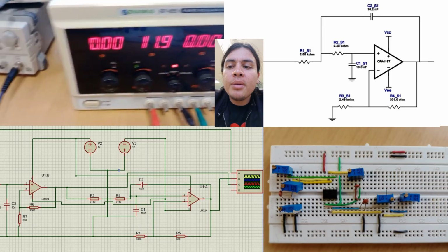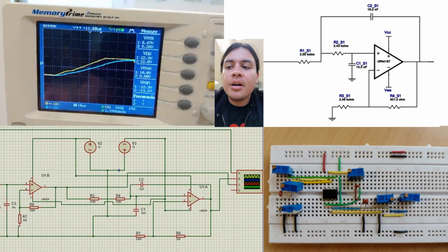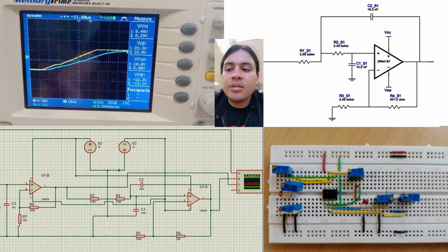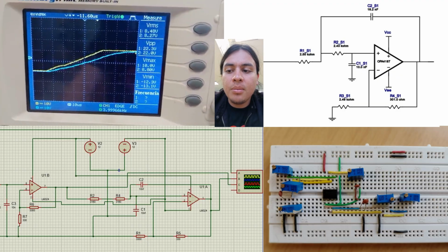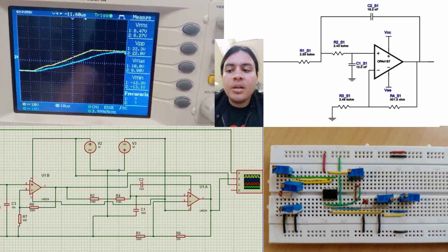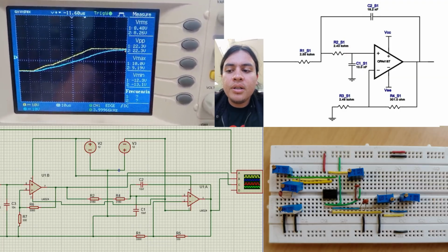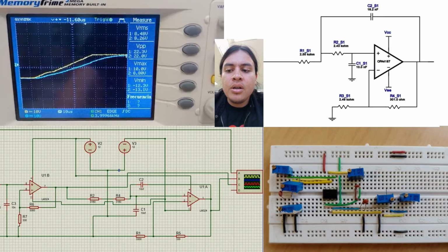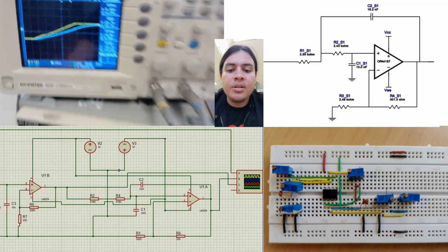When we modify the feedback resistance, we are altering the circuit gain, and consequently its stability margin, and this way the system can operate under stable, marginally stable, or unstable conditions, depending on the chosen value. This highlights the importance of carefully designing the feedback network to ensure reliable filter operation and avoid unwanted oscillations.